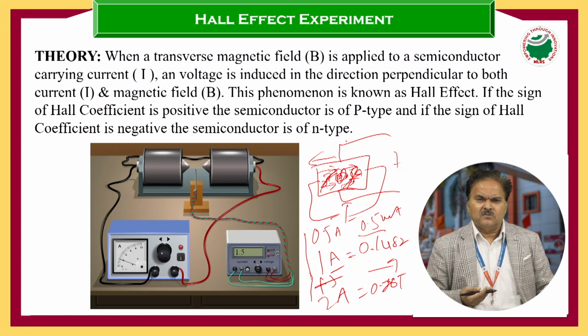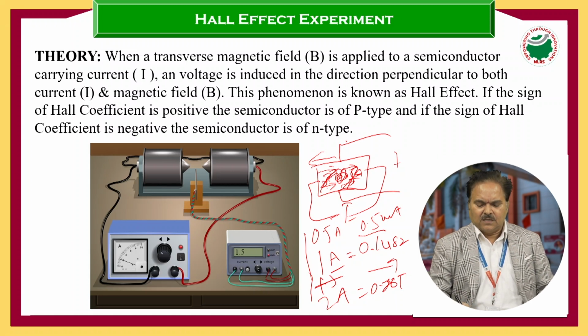So how is the voltage induced? In the lower position, the carrier concentration, the electrons or holes, is higher, because the path of electron movement is deflected toward the lower direction. Because of that, the bottom plate will have more electrons and the upper one fewer electrons.